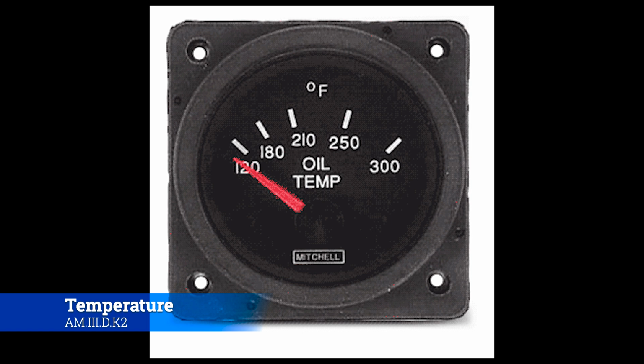And so as it starts to not be able to hold as much heat, the aggregate temperature of the oil itself starts to come up because it's not able to grab that heat and then disperse it as it goes. So it just starts running hotter and hotter as that oil goes through the engine and returns back to the sump. It's just super hot because it's not able to grab that heat and then bleed it off into the system.